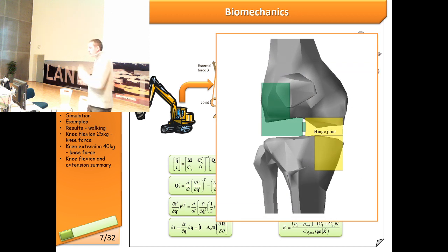Now, let's say that you look at the knee, and you can model it as a hinge joint. So that's one of the simplest approaches. You build one beam in your simulation software, you make another beam, and you apply their properties. You don't really care about the shape in that case. You care about the inertial properties. So the center of mass for every part is important, the total mass of the part is important, and then moments of inertia are also important when the part is rotating, so that it would know how much resistance it's causing and how much torque or force you have to apply to move it.